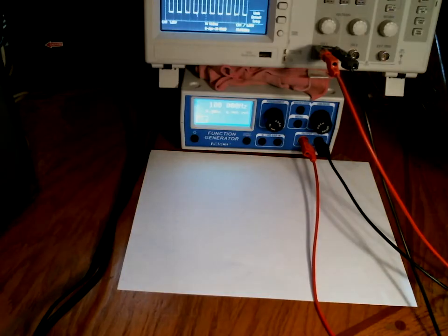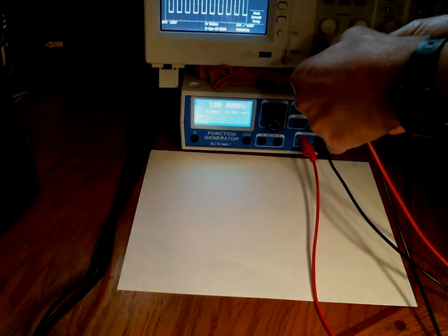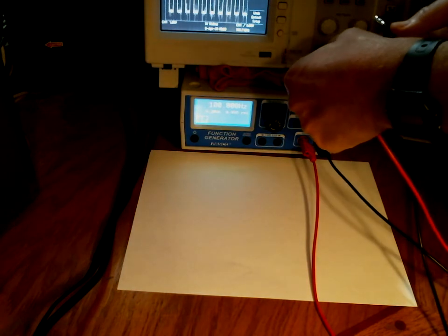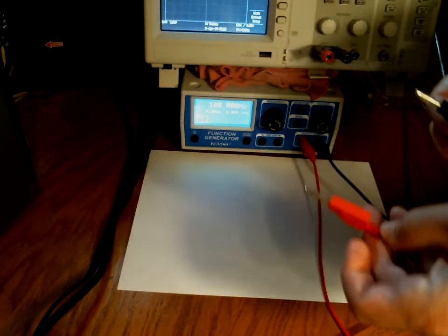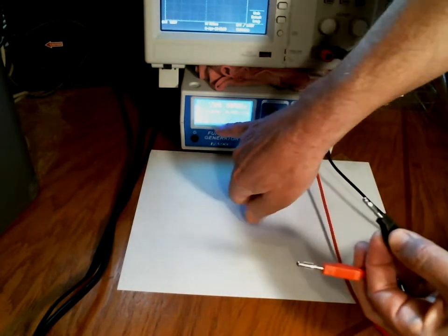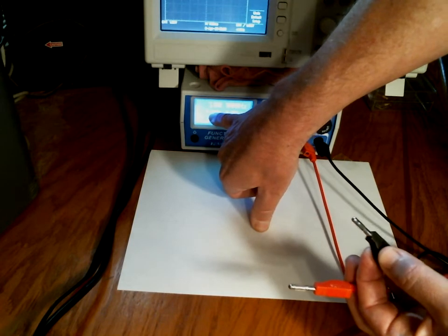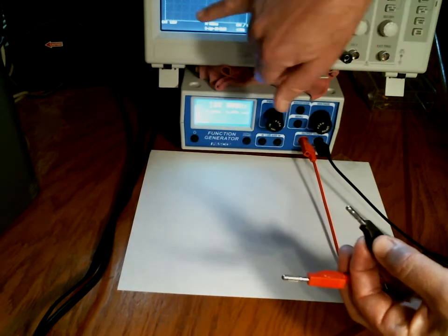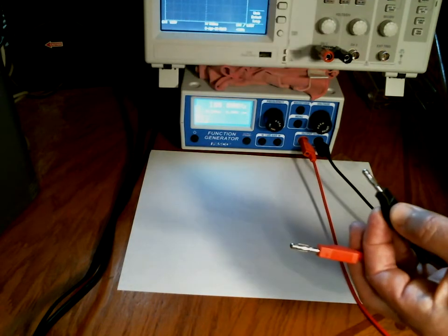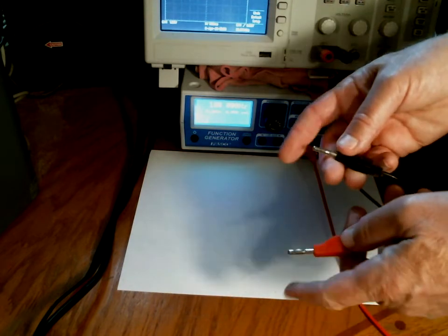Now I'm going to go ahead and build my actual circuit. I'm going to disconnect these banana plug cables here. And I'm not turning down the function generator yet, just to demonstrate that it is safe to go ahead and touch these conductors. If you look on the amplitude here, it was at 0.3 of a volt, which is not going to hurt me. I can also verify that on the scope. The volts per division on the scope were 1 volt. So these are small voltages, so I can touch these. I don't feel anything. I don't get shocked.